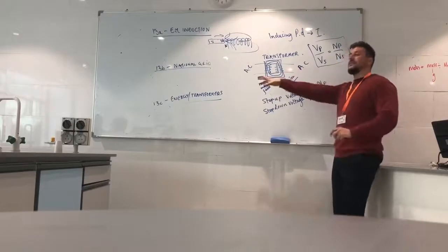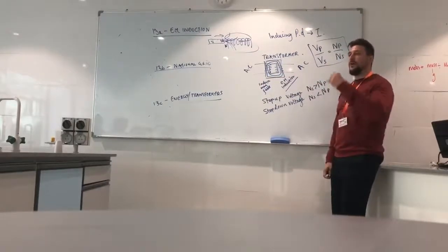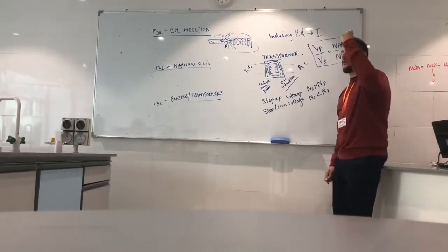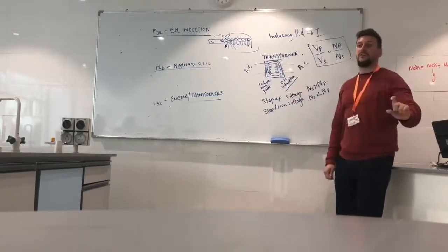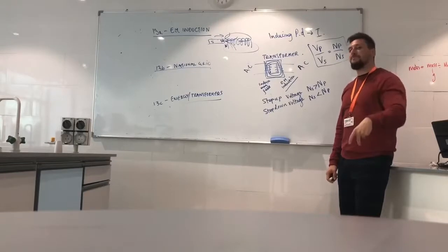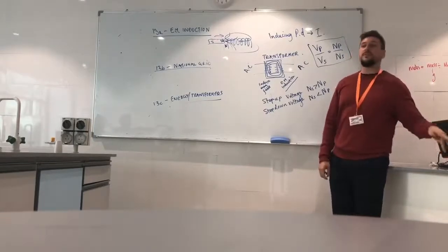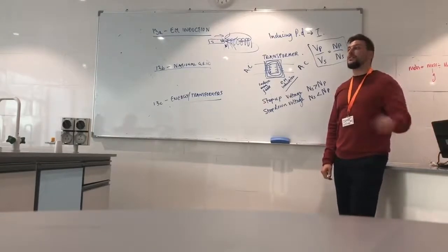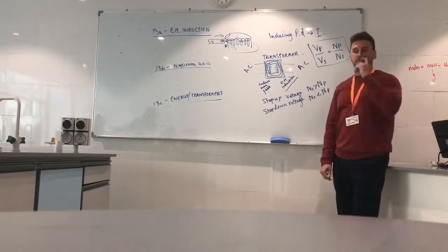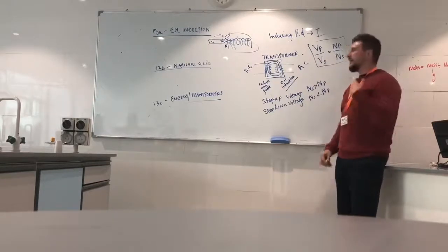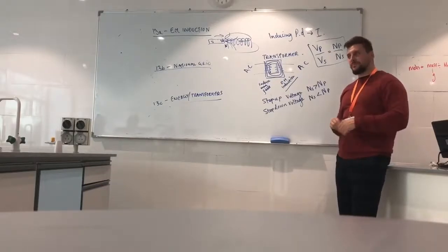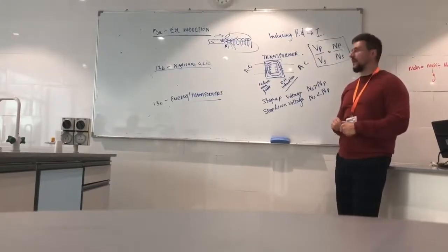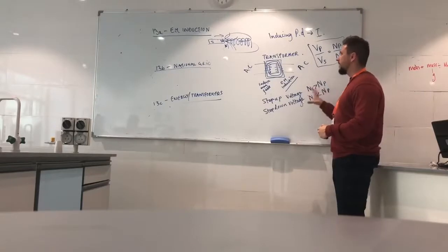We get to the end of the transmission lines, we step down: 33 kilovolts for factories that are big, 11 kilovolts for factories that are small. We carry on from the first step down, we step down again to 230 volts for mains voltage in homes, schools, offices, etc. The main reason we step down to such low voltages is for safety and for increased current. That's 13B, the national grid.